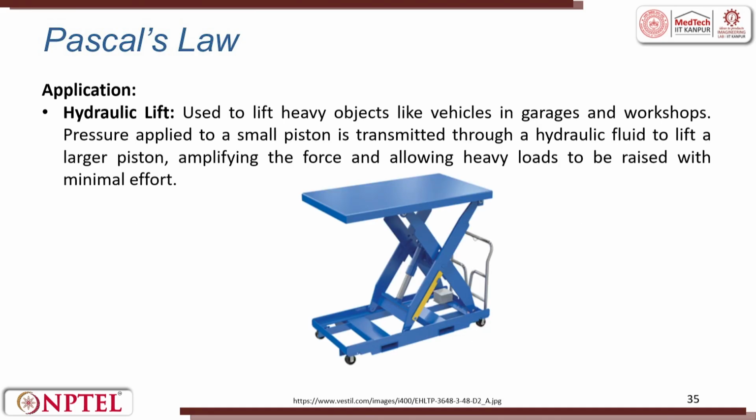So, some of the applications of Pascal's law is the hydraulic lift, used to lift heavy objects like vehicles in garages and in workshops. The pressure applied to a small piston, so you pump it, is transmitted through a hydraulic fluid to lift a very large piston. So, this is a large piston. Applying the force and allowing heavy loads to be raised with minimal effort. So, wherever we use hydraulics for lifting, locking, holding, we use Pascal's law.